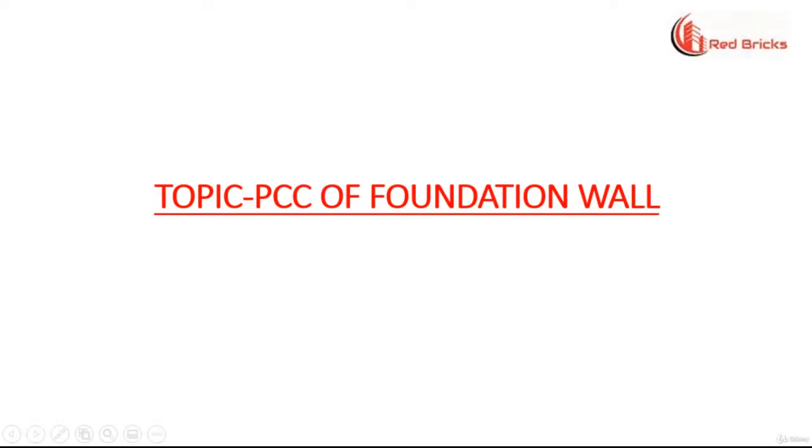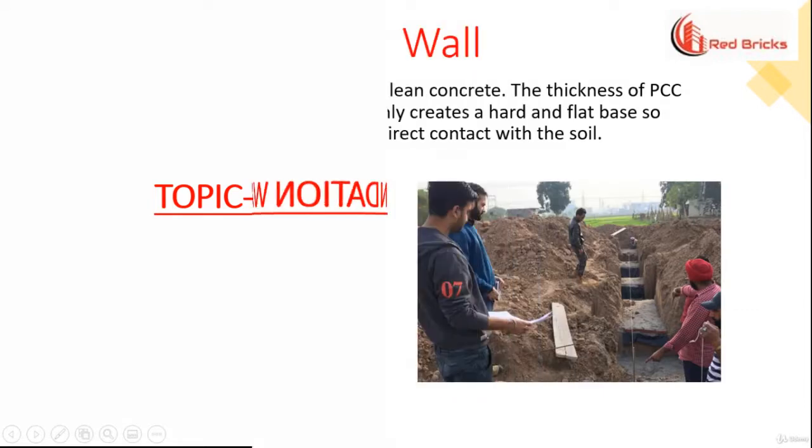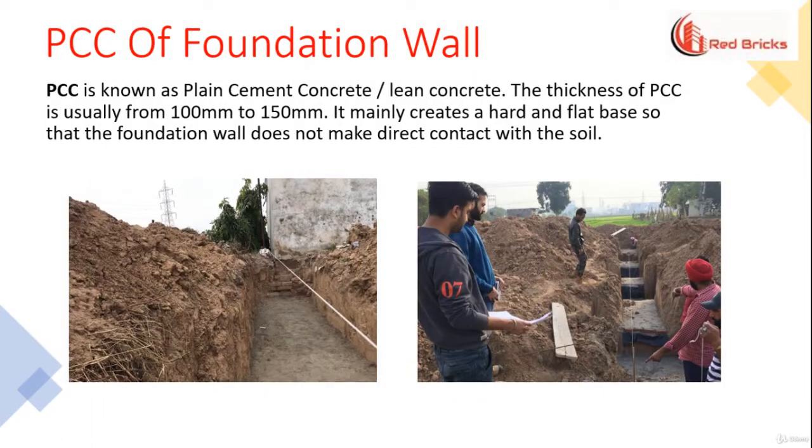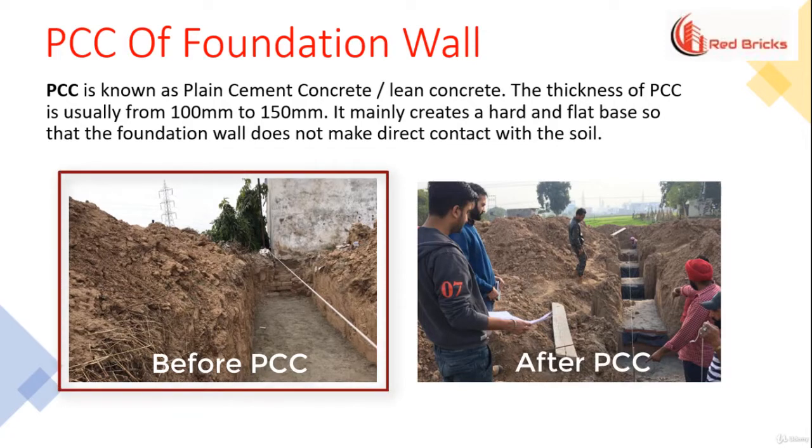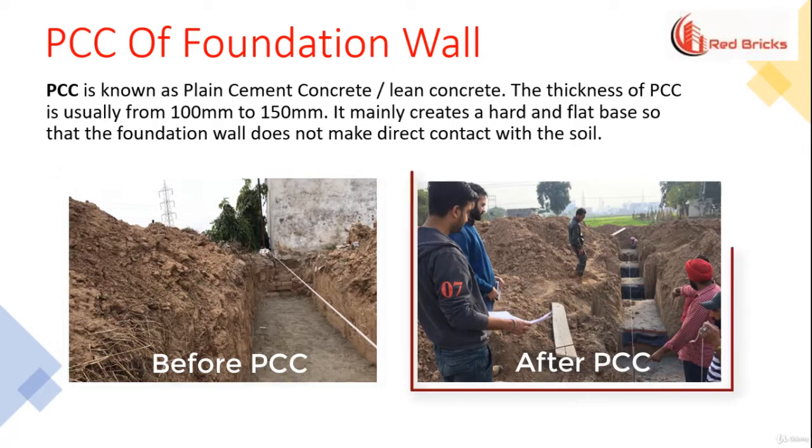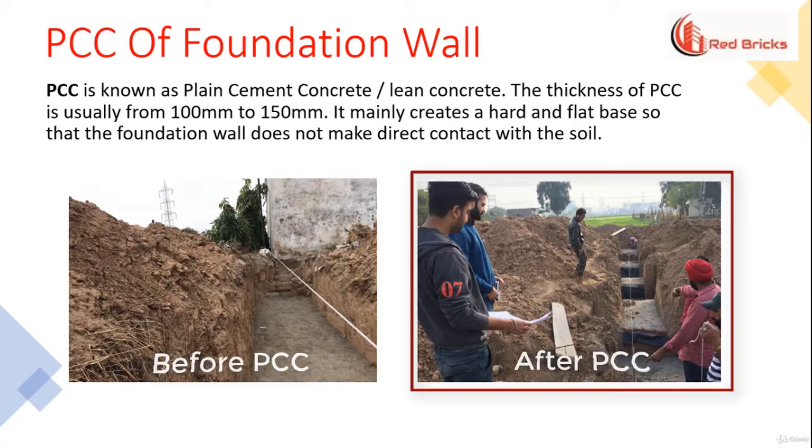Hello students, in this lecture we are going to find the PCC quantity of foundation wall. In the previous lecture we had discussed about PCC. One important point about PCC is that its thickness is from 100 mm to 150 mm. Here you can see the excavated base of a foundation wall on which PCC layering will be done. The picture on the right shows a foundation wall after PCC covering.